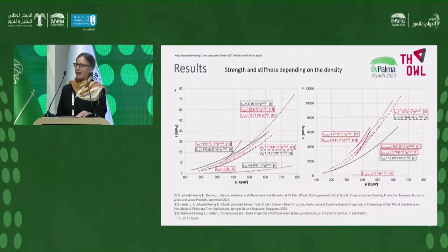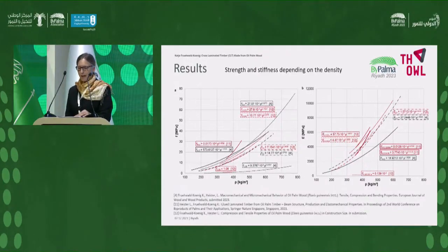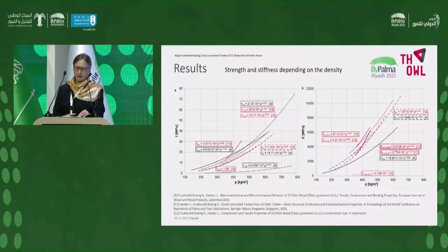So the size does not influence the strength values, because the elastomechanical properties depend on the anatomical structure at the microscopic level. Main influencing factors are the density, but also the age of the palm, the location within the trunk, so the height and the cross-section, and probably the oil palm subspecies, differences between individual palms and plantation sites.